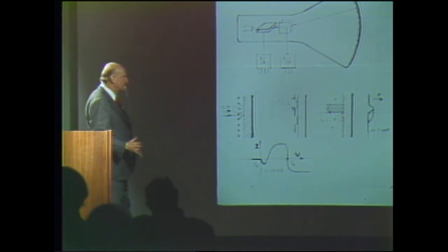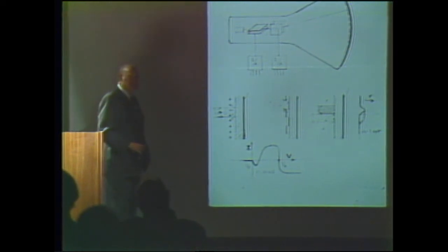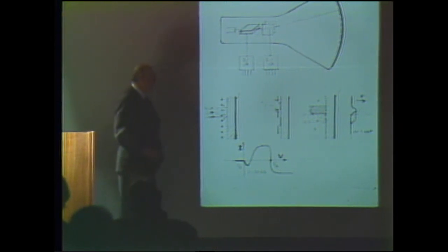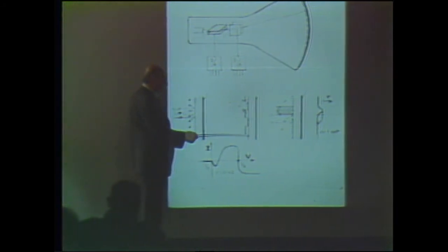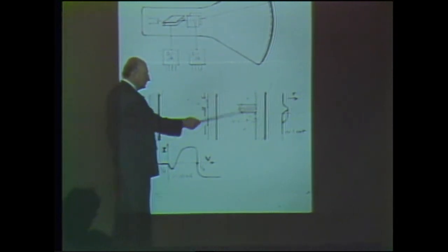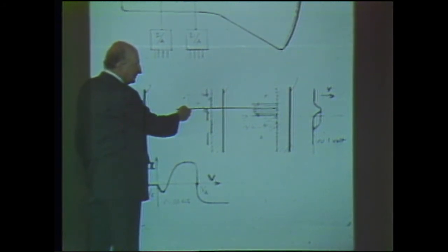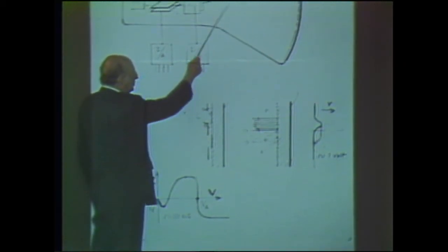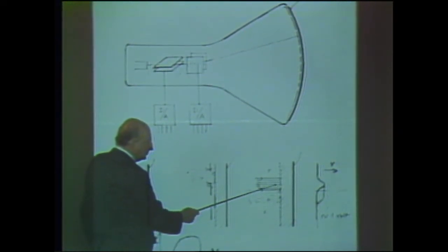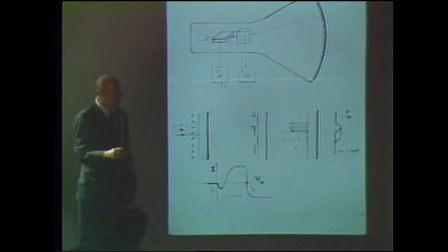And so Professor Williams at Manchester thought that maybe he could get away with no structure at all, and in fact take advantage perhaps of the instabilities that were noticed here. And he imagined using a perfectly ordinary cathode ray tube, the only thing being that its face was painted with metal. When he bombarded a certain area, the secondary electrons went away to the walls of the tube, so the area became positive. And if you went to another position, it simply remained positive, because the insulation was good enough.